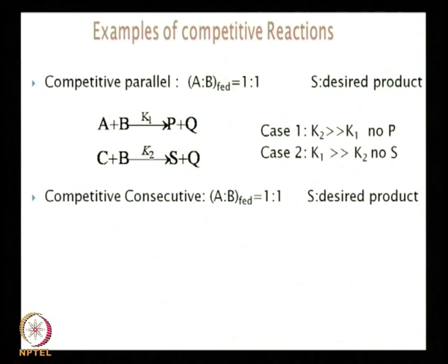Sometimes the simple solutions escape you when you're thinking of something too complicated. There is a simple way. Making residence time very low still wouldn't help, because, as you have studied in reaction engineering, it will produce only in the ratio of S to P. The yield of S to the yield of P is going to be in the ratio of K2 to K1, independent of the residence time.